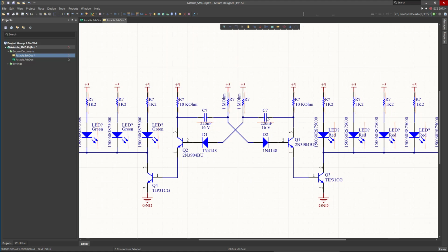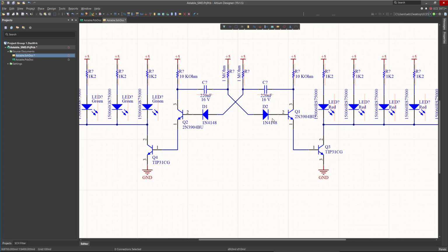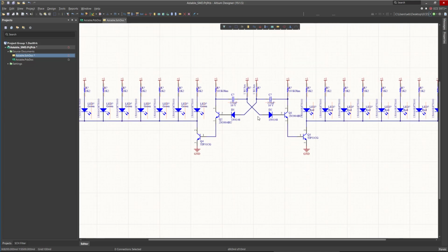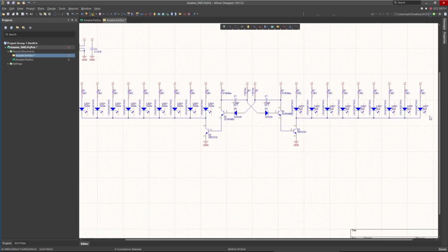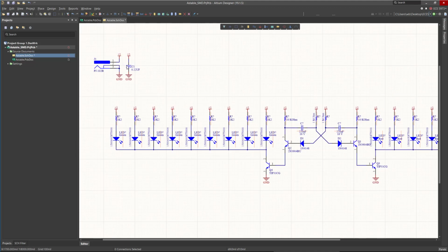So I don't want to copy and paste wrongly from the low voltage to the high voltage, and if you apply high voltage on a low voltage rated cap, it will blow up. So we don't want to do that. So I keep the voltage parameter on all the time, just to have an insight into the cap rated voltage. Now what's left to change is these transistors and the diodes.